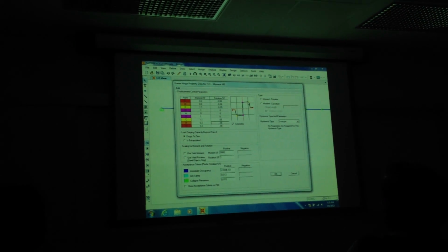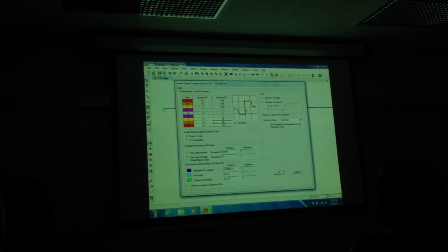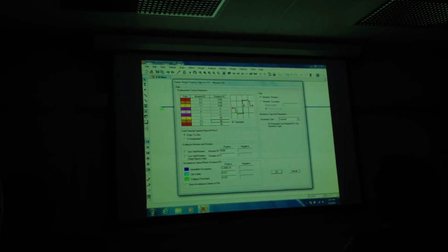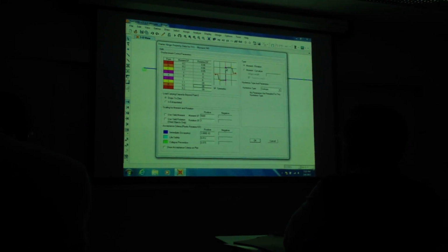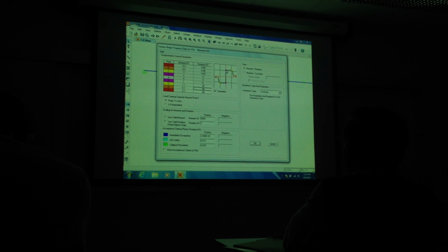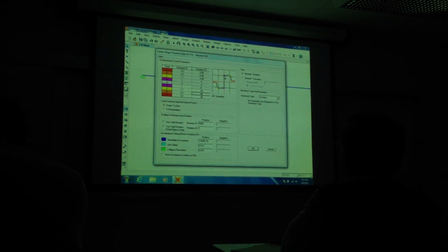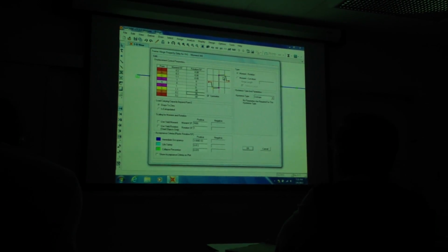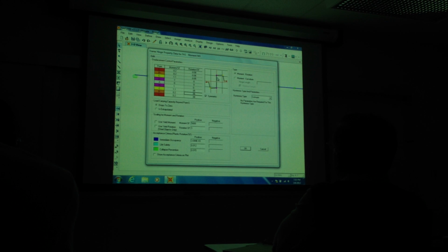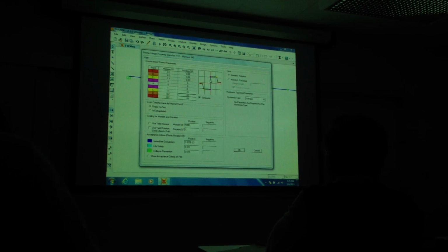But prior to reaching that, in both directions, what happens is linear elastic at first. It'll go up and down here, the moment will, without any rotations. See how it's 0? And then if it exceeds this point, the moment gets larger, it suddenly takes off and goes this way. But then when it unloads, it won't come along this curve, it'll cycle. Form a hinge that cycles around. And it's the area under those curves that would take energy out of our system properly.